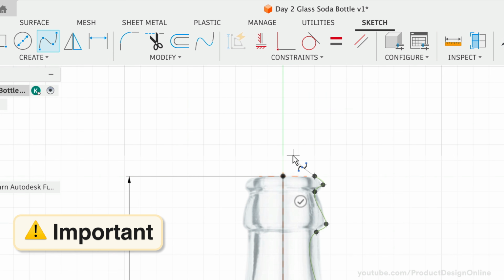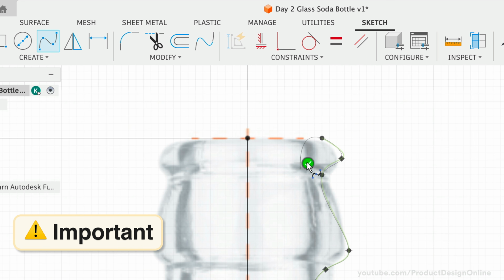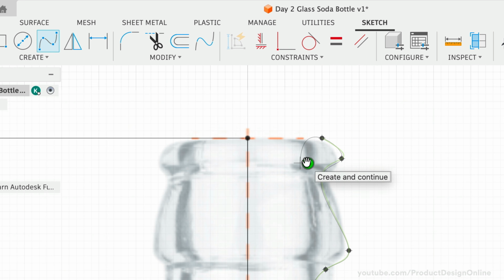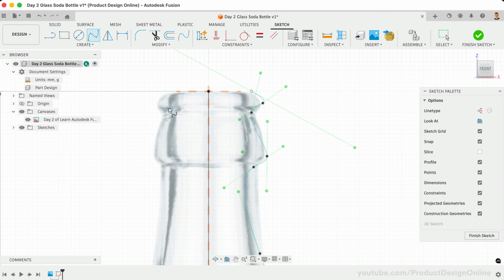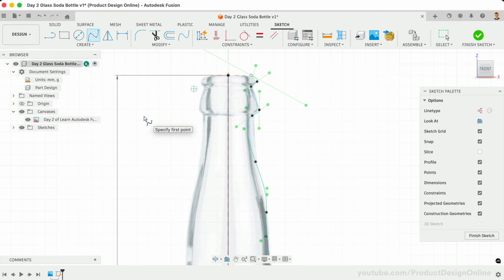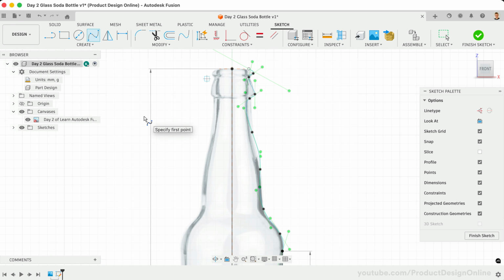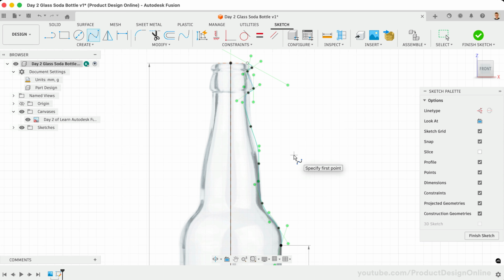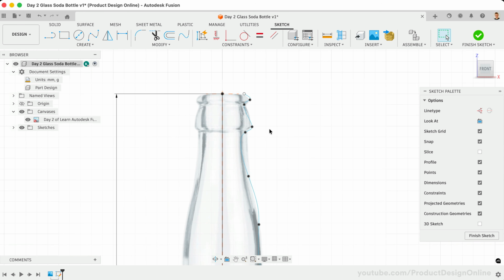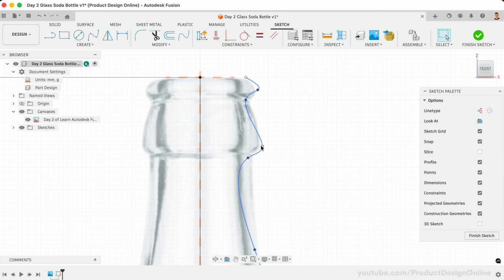Once you finish placing points, press the Enter key or select the green check mark icon. This step is very important. Pressing Escape before you end the tool with a check mark or Enter key will delete your spline geometry. Now, take a minute to clean up the spline. Each spline point provides a handle to adjust the curvature. Press Escape to clear the command. Click in space to deselect the spline, which hides the handles. Before you move those handles, click and drag the points themselves to reposition them. This step alone can improve the curvature.